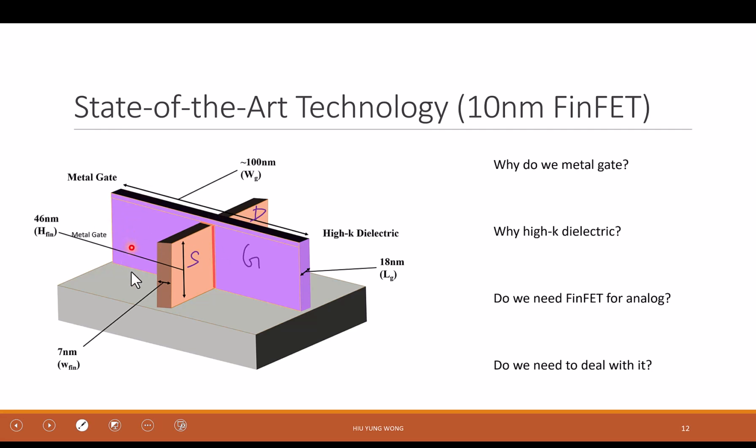So you see that this is a metal gate. What it does is, here, the red one is still the oxide, insulating. And then we wrap it with the metal gate, with a conductor, which is the gate, so that it can control it electrostatically. They are not really pinching like what we're doing with the water pipe, right? They just use the electrostatic force to turn on and turn off the current. And that's why we have the so-called 3D transistor. And this is called FinFET.